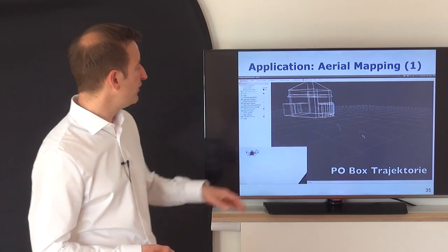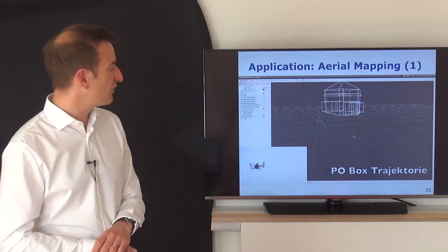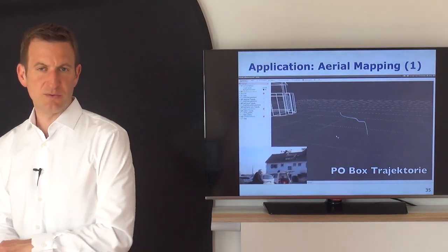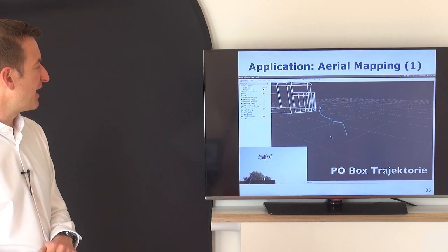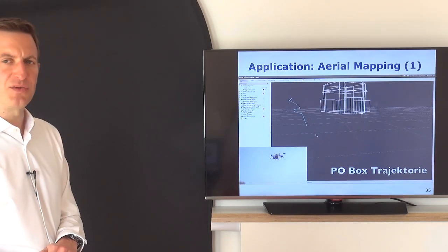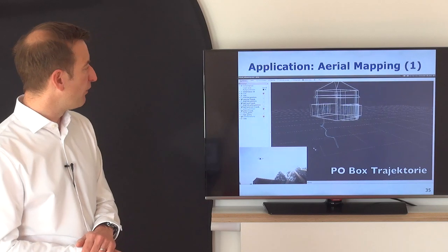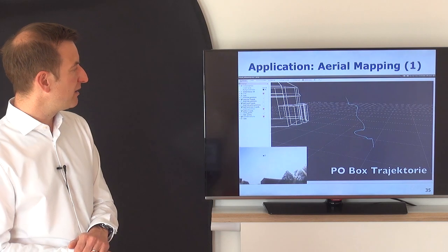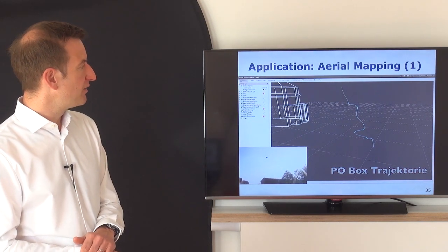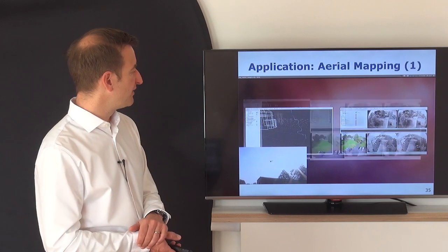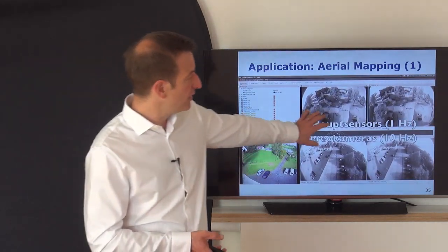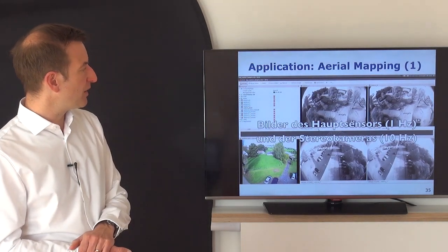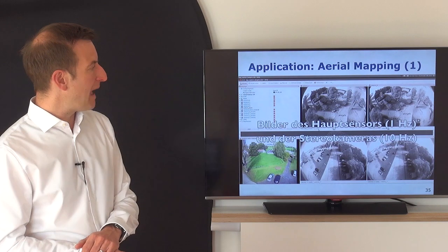And so what you see is a UAV which flies over the environment, and you see here a trajectory estimate which is done here using GPS and IMU information. At that point in time, this is the work done by Heiner Kuhlmann's group for estimating the trajectory of that UAV. And then we can also use camera data to enrich the sensor data with camera information. In this case, these are 2 stereo cameras and a high-resolution color camera as a monocular camera, and then perform aerial mapping using this data.